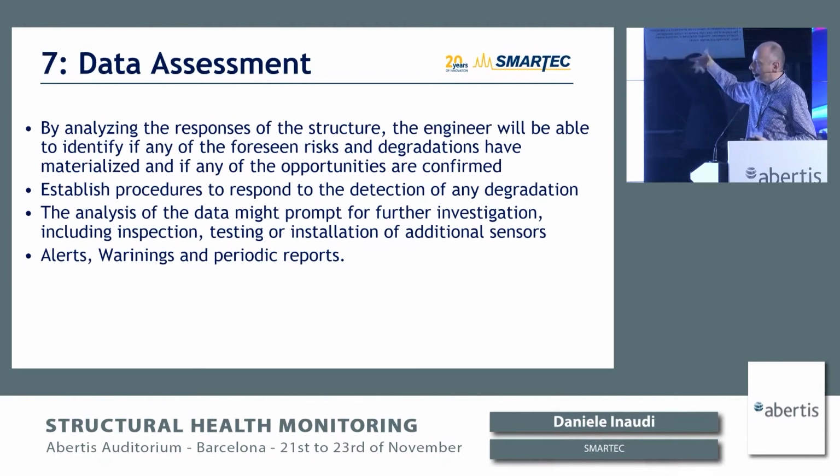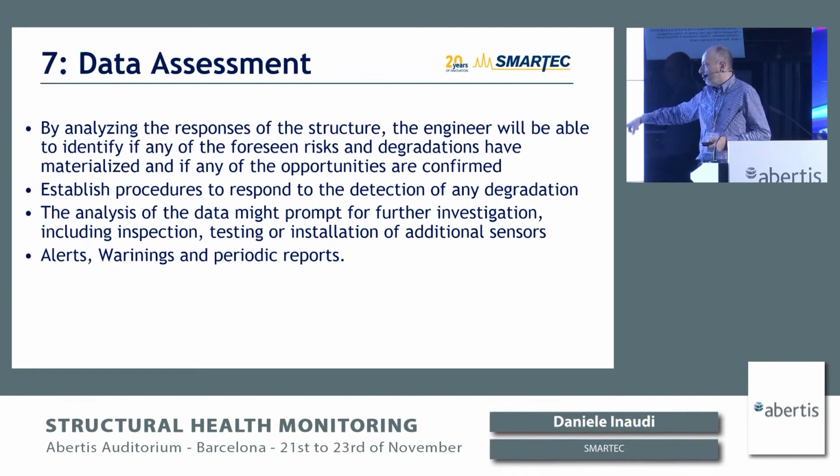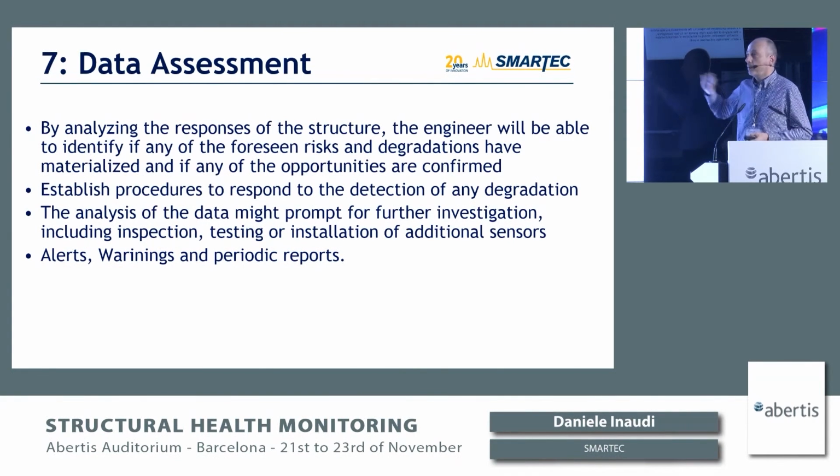So the risk assessment also helps in the data assessment, to make sure that when you measure something, you know why and what is the probable cause of that result. Establishing a procedure to respond to detection is very important. I always tell people never set a threshold or an alert if you don't have a clear plan of what to do when that alert goes off.